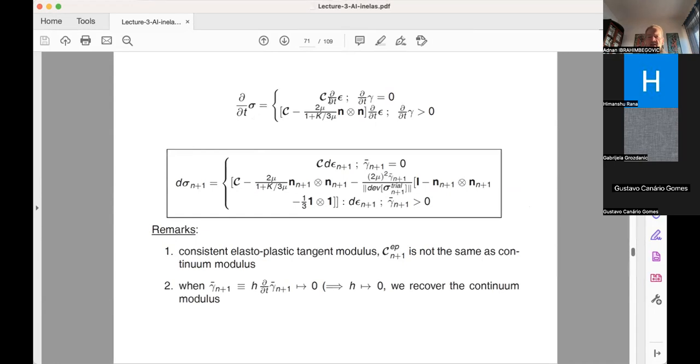of the elasticity tensor. However, in the discrete setting, what is really done is first you have to discretize. In other words, you have to take into account all the equations that you are using when you're doing your time integration scheme with the operator split and so on and so forth. And then you linearize to get really the true elastoplastic tangent modulus in the discrete setting. And you can see that these two results are not the same. Namely, in the discrete setting, we have an extra term, which is all the way here, which actually allows us to have truly quadratic convergence property of Newton's method.